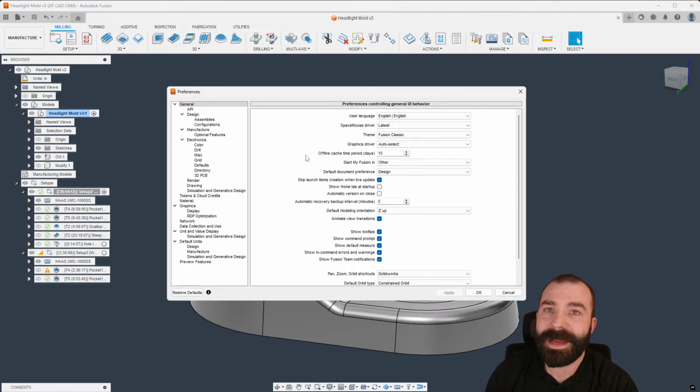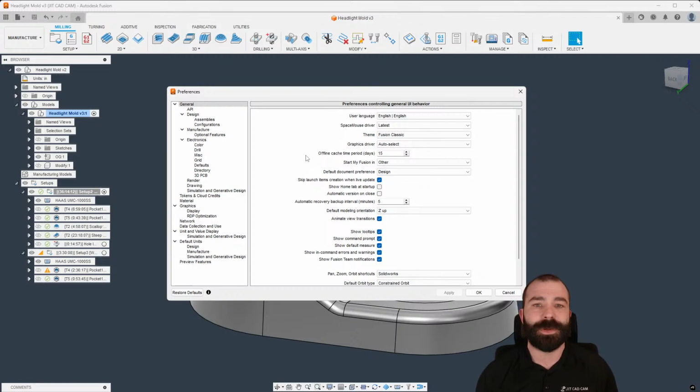So from there, we can pivot to a few more things while we're sitting inside of here. Now, this is one I think a lot of people overlook: when you're doing a lot of things inside of Fusion, you're stacking your offline cache. Every time you open and save a file, there's a local saved version, and then there's a backed up version that goes to the cloud, right? The reason for that is so you can quickly access commonly accessed files on your desktop without the need to download and pull it into the software and do all the witchcraft in the background. But the big thing about this is we can change the number of days that it actually sits on our computer. Again, this helps a ton.